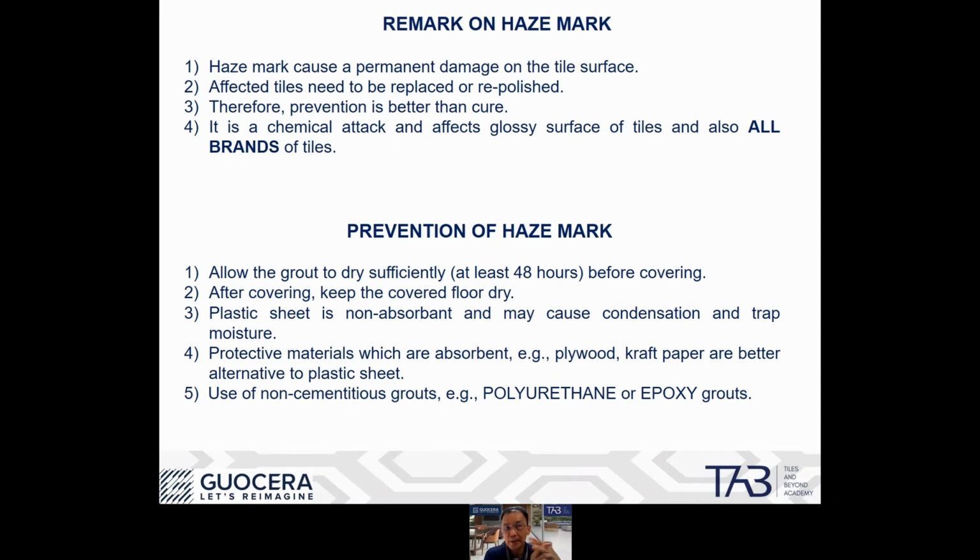So again, it is a chemical attack. It affects the glossy surface of all tiles. Now you may be asking, do matte tiles actually have this effect? It does happen, but because they are matte tiles, the attack is not so obvious, and when it's not so obvious, nobody complains. Because the polished tile surface is so glossy, the attack is more obvious. It actually affects all brands of tiles, even Italian tiles, because it's a chemical attack.